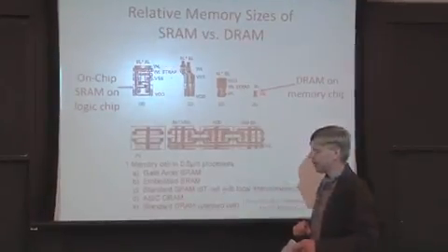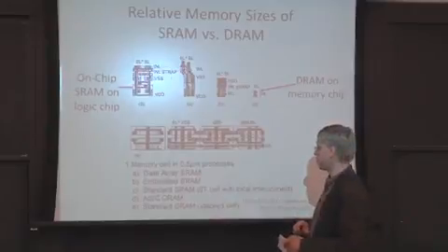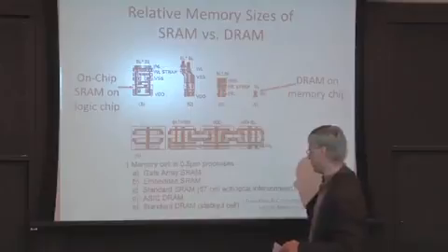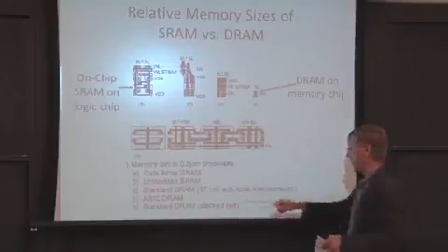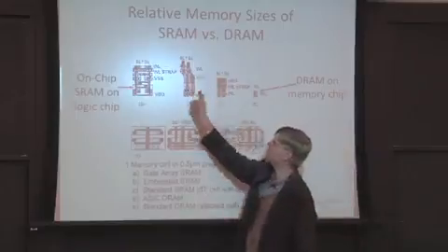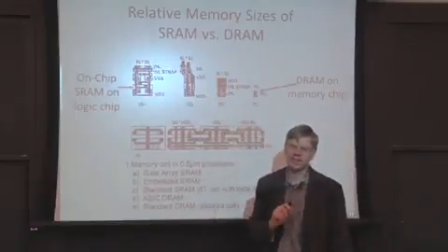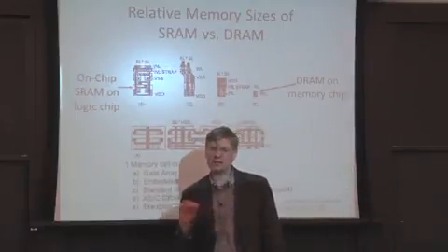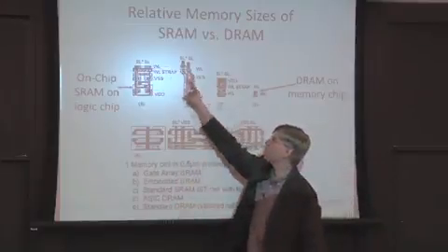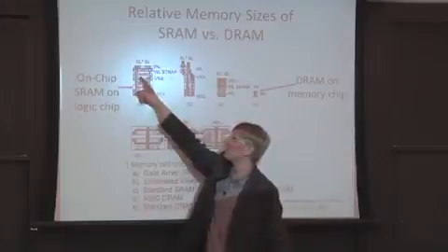And some other interesting things on this diagram: we have SRAM on a traditional ASIC process, which is here. Here we have a 6 transistor cell with local interconnect. It's a little bit smaller. What is meant by local interconnect is that you can use the poly layer, the polysilicon layer of your process, to do interconnection, so you don't have to use wires for everything.